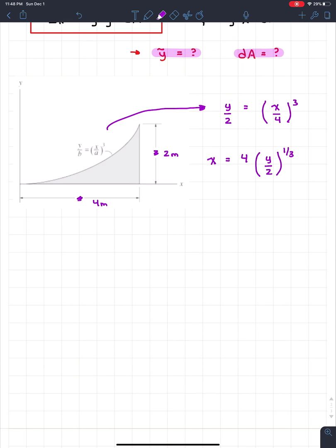So normally what we would do to find these values is we take a slice. And that's exactly what we're going to do this time. We're going to take a slice. But remember last time we encountered kind of a funny situation where we can take a horizontal or we can take a vertical slice. And both of these will give us the same answer in the end, but one of the integrations would be a little bit easier. And as you guys will see, the exact same is true for moment of inertia. However, I'm going to tell you guys what I would call a little trick, but this is what I like to do, and it usually makes things easier. Very rare cases where it doesn't, but usually does, so this is what I like to stick with.